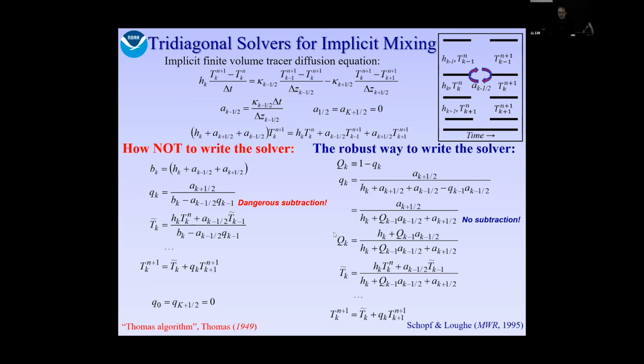We took that tridiagonal solver and used it as a way to detect which chip was bad because it was so very sensitive to random fluctuations at that last bit. It was failing routinely. The MOM6 algorithm on the right would never have detected that because in this case, we're not taking any differences. The answers always have the full 16 decimal digits of precision without having to worry about some of the problems that can arise with round off.